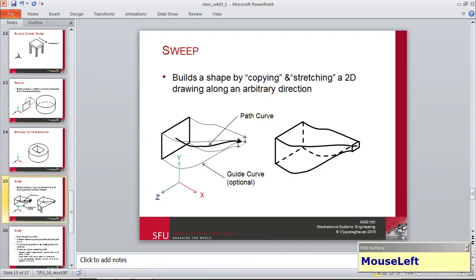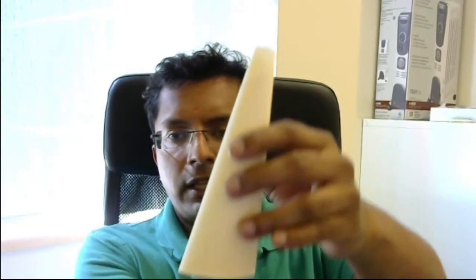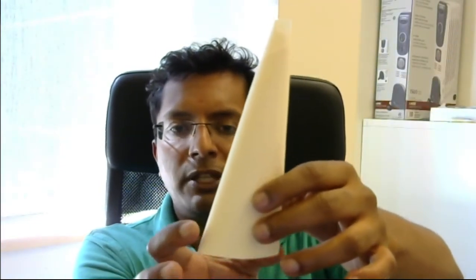The next thing we're going to focus on is something known as a sweep. So sweep is basically used to create an arbitrary shape. So you can imagine if I wanted to create this cone, and then imagine that instead of a straight cone, it's actually kind of like a weird squished up cone. The bottom here is an ellipse. The top here is an ellipse in a different direction. So what I can do is basically sweep this particular curve along this particular way.